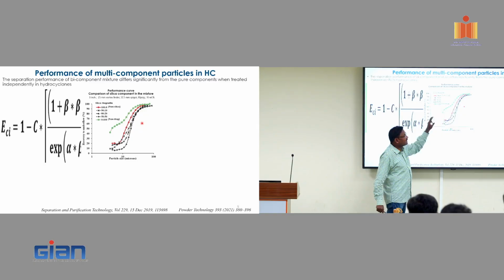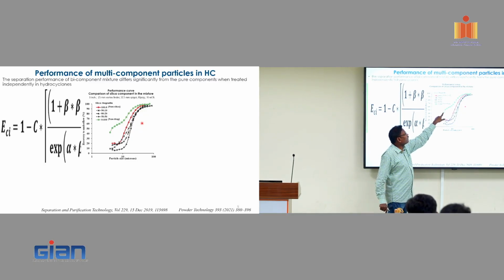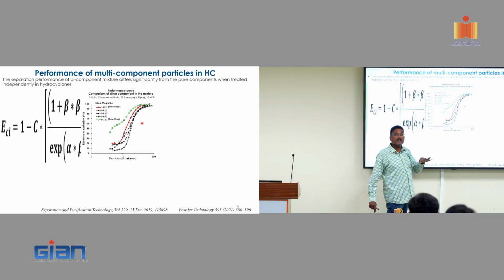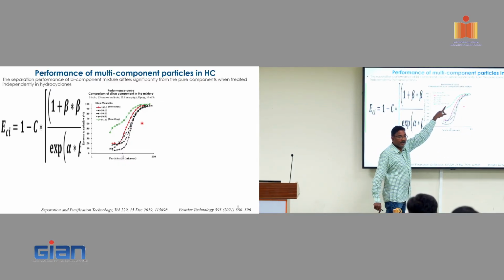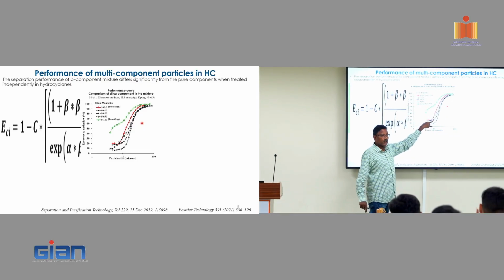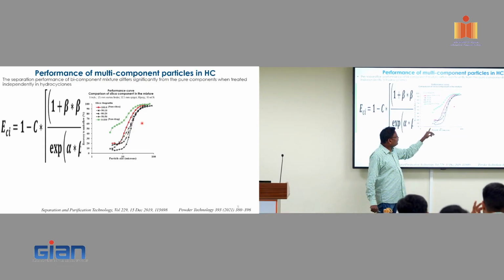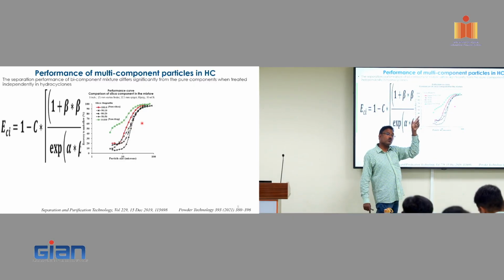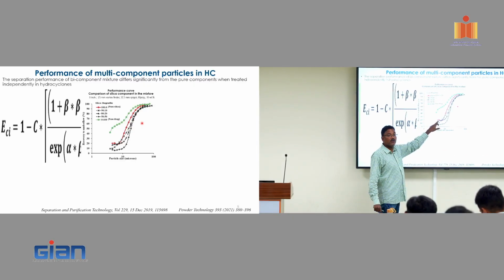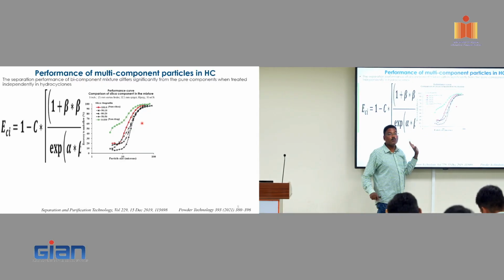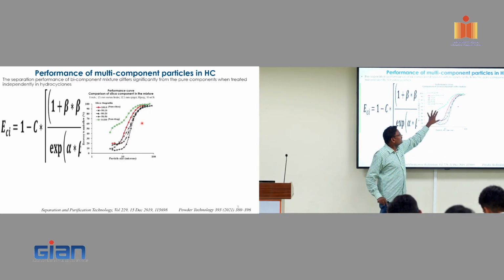Now when you are running the pure heavier component, recovery is not very efficient, but the maximum recovery to the underflow comes quite quickly. Whereas for silica, there is also some fish hook phenomenon that happens. That means even though some of the fine particles are supposed to go to the overflow, they also get trapped into the underflow. That is for the pure component. Now, these are well established.